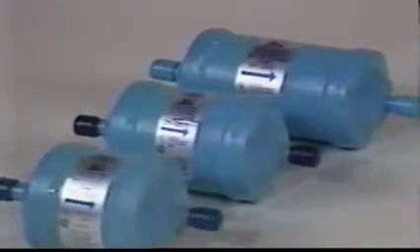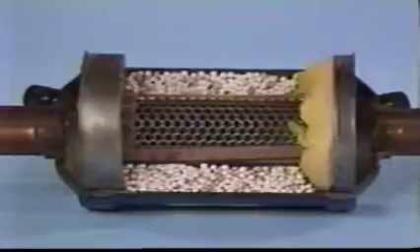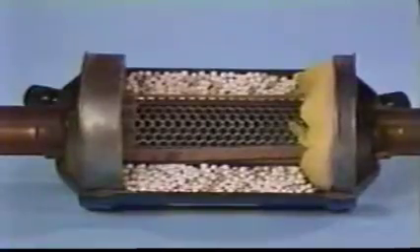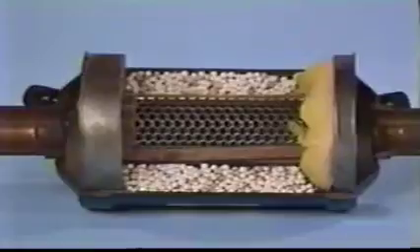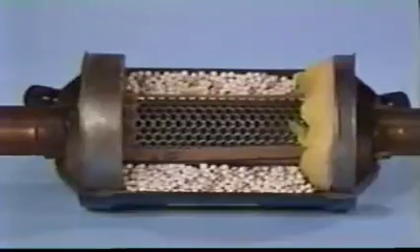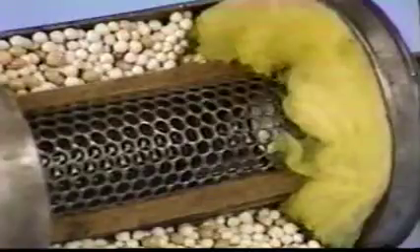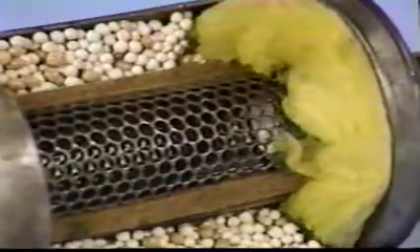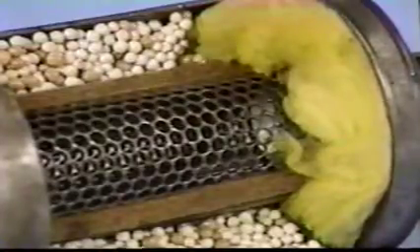In suction line filter dryers, the big need is for filtration, since it is the solid contaminants that are the most harmful to the compressor. The drying function takes a back seat to filtration in the design of the suction line filter dryer. In fact, in some applications, the dryer element is not used, and the result is a component that is all filter. The filtering action of the suction line filter dryer is very high, with the capability to remove solid particles as small as 10 microns, about the size of the diameter of a human hair.